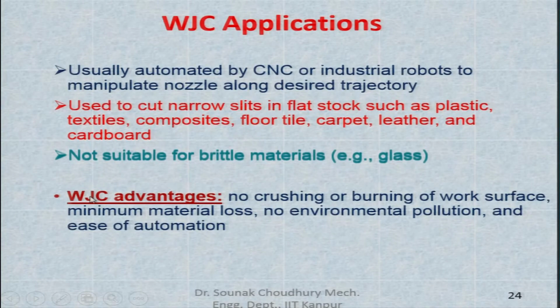So, what are the jet cutting advantages? There is no crushing or burning of the work surface, because no temperature is involved here. There is minimum material loss, no environmental pollution because nothing is released to the atmosphere, and ease of automation. We have ease of automation because we can have computer numerical control and program it so that the nozzle moves through a very complicated path, like the tool moves in computer numerically controlled machines.